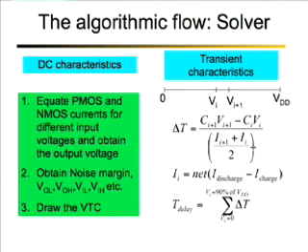So if I have an inverter driving a capacitor, we should have the NMOS discharging the capacitor and at the same time the PMOS charging the capacitor. So we should essentially be looking at the differential current, which is the difference of current between the NMOS and the PMOS, and that is exactly what we provide in the simulation environment. In this way it can actually give you a good estimate of the influence of off current or the offset current on the delay characteristics of typical cells.